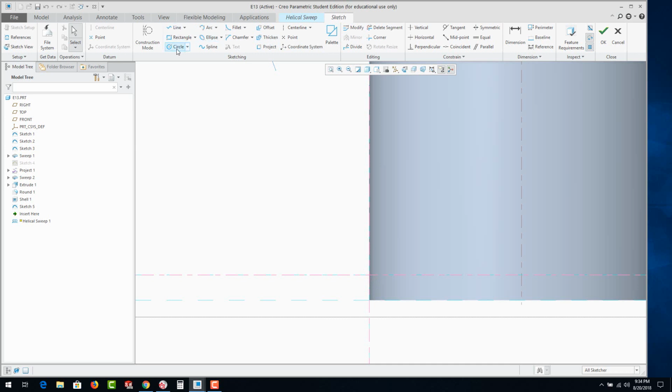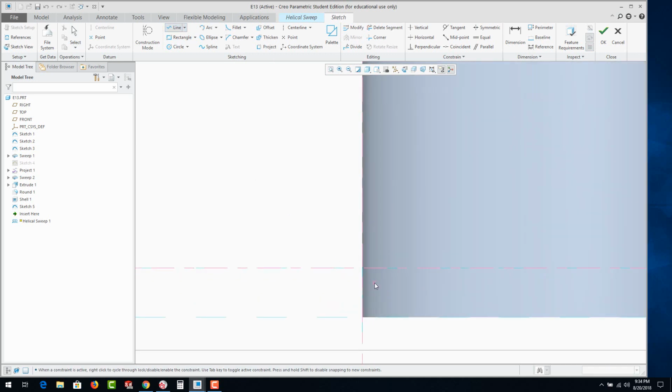And if you want to make it simple, you could just draw a circle right at that point. Otherwise, you could actually take the line tool and make a traditional thread that you would see on a soda bottle or any sort of bottle. I'm going to draw this in, and it's a good idea to have it intersect into the actual neck of the bottle. If you draw it right on the edge, sometimes you'll get little errors because it tries to merge the geometries and it can't.